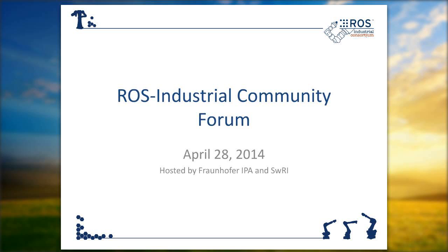I don't know if maybe the question about cascade controllers means concatenating, feeding the output of one controller as input to the other in a sort of computational graph layout. So this is not currently supported in ROS control. Things like perception or control pipelines have been discussed quite a lot in the mailing list, but the current interfaces do not allow you to do that. If you wanted to do it, you would actually have to bundle all of that code inside one controller plugin. That would be it.